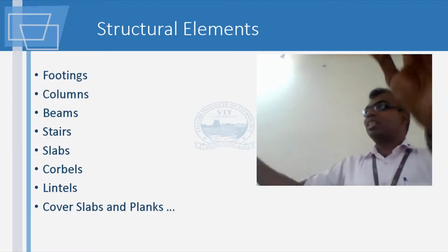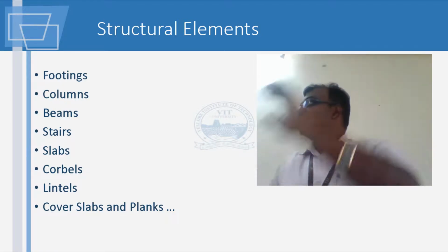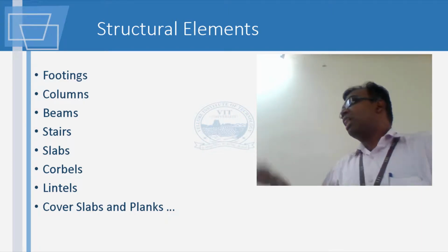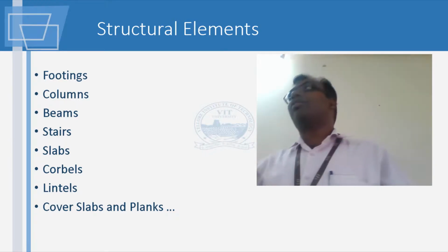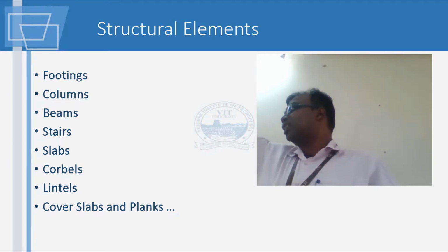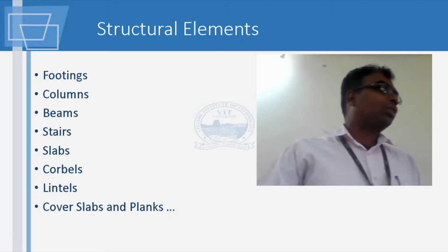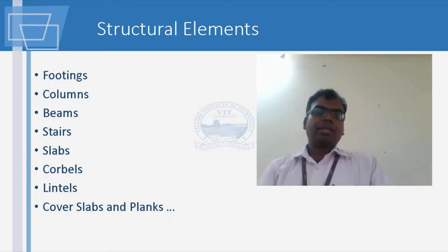Okay. How is it running? It's running on two steel beams. The steel beams rest on a projection from the column. That is called a corbel. You can see corbels in many of the old constructions for supporting the roof and things like that. But nowadays corbels are restricted to applications like what we have in our CDMM building.